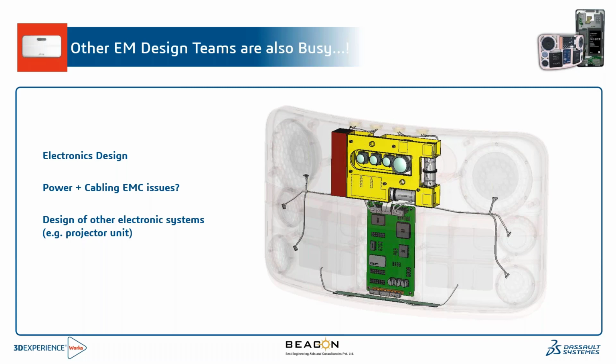Since we have PCB and packages, we can perform the analysis for electronic designs. If I have to check signal integrity, power integrity issues, or design rule check issues, then coming to the power or the cabling issues, we can see what the crosstalk is, or we can see what the EMI/EMC issues are, if there is any radiated emission, conducted emission, or susceptibility, which I have to take into account.